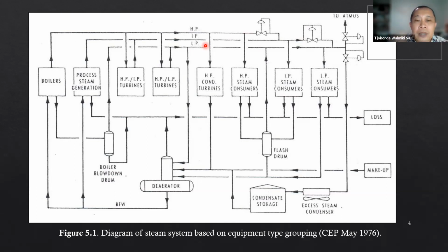Okay. So steam, water vapor is aggressive to compressors. Yeah. So we typically do not compress steam, but we produce steam at the highest possible temperature and pressure, and then reduce the pressure gradually as needed.